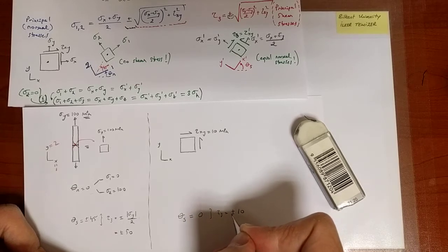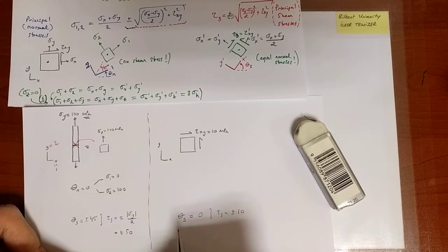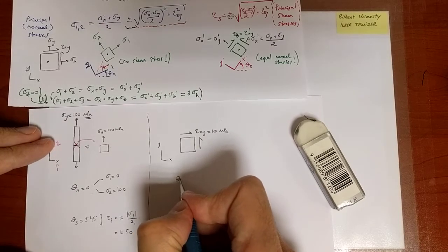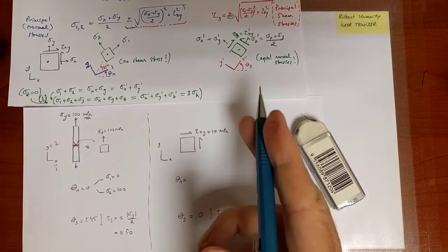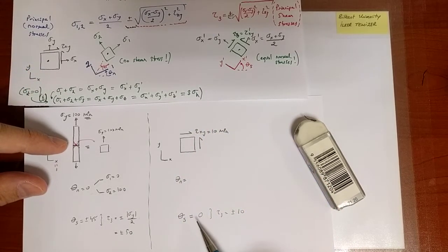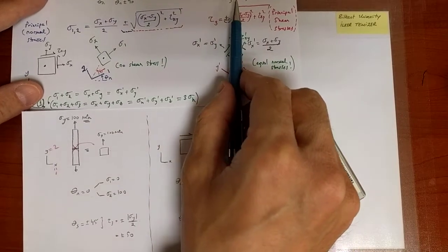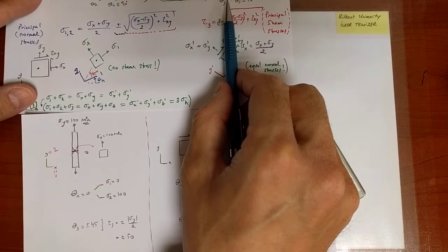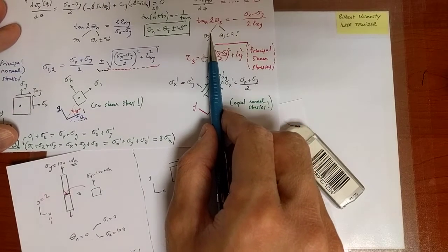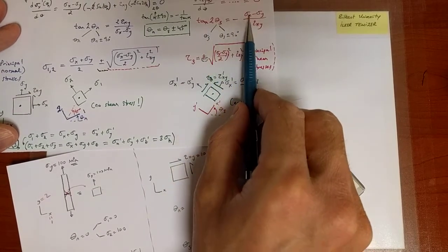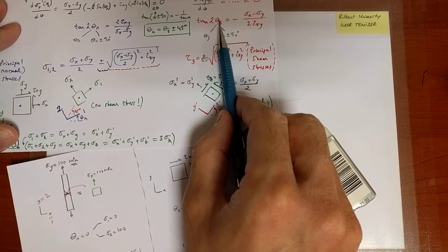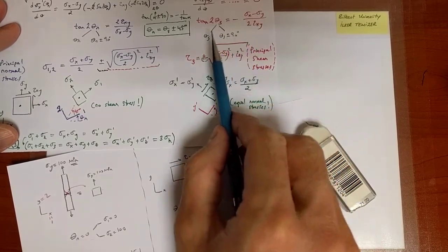Let's come back to what this plus and minus refers to, but before that, I will go back to the theta setting. We could have deduced that theta s is equal to 0 by looking at this equation over here. In that equation, sigma x and y are both 0, so this is 0 divided by something, and therefore theta s must be equal to 0.